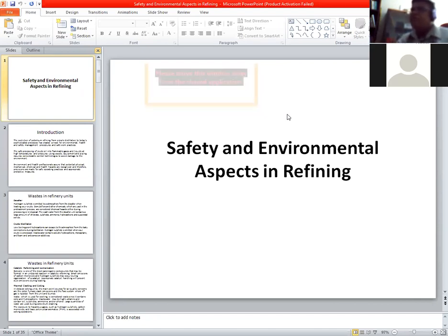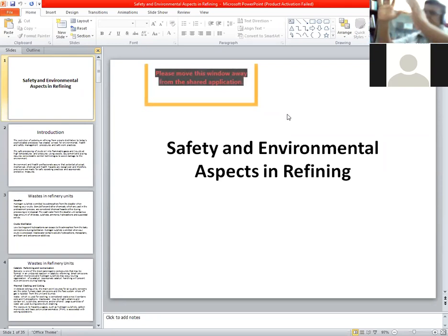So we should not allow poor connections wherever you are working in a petroleum refinery. If you find that there is some leakage, especially hydrocarbon steam, it is still okay, although it is economically a loss. If there is leakage, the first thing we can say is that we are losing something. So leakage should not be allowed, especially hydrocarbon leakage, because this hydrocarbon, leaking as vapor or gaseous form, can accumulate in the air, and once upon a time it can self-ignite.